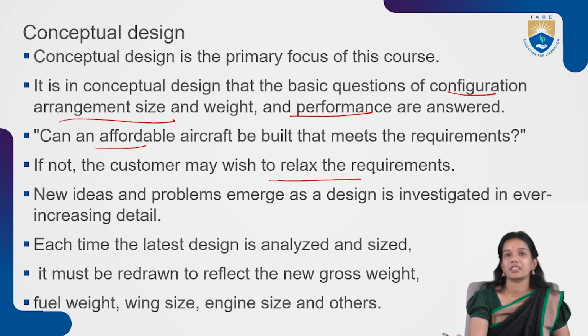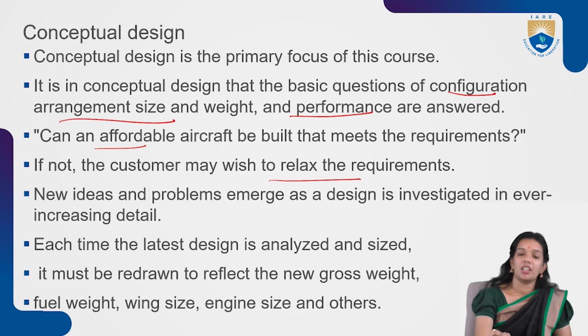Relaxing the requirements is needed where the customer has given so many different approaches, or so many inputs. When the designer starts deciding according to the inputs, maybe the wing is large, or if the overall aircraft is going to be very large, then it is not going to get the efficiency it should have got if only you had relaxed the requirements. So the designer would ask the customer to relax the requirements, let me not use some of the specifications given by the customer. Let me relax some of this, then we get a better output. A better aircraft is going to be designed or manufactured, right?